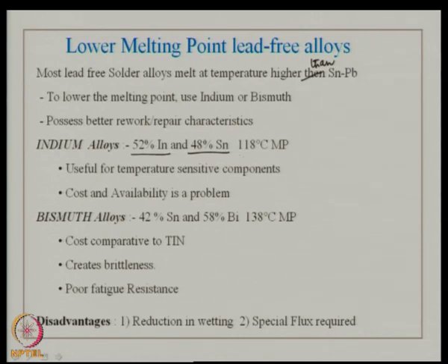You can see the melting point is quite low, lower than the eutectic tin lead, useful for temperature sensitive components. This is the ideal application, because today in certain electronic products, the components being used are sensitive to higher temperatures. Cost and availability is a problem.